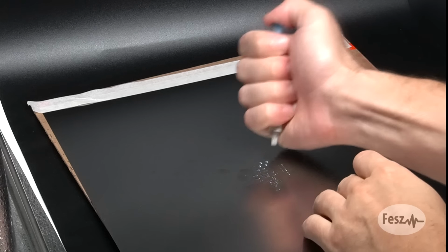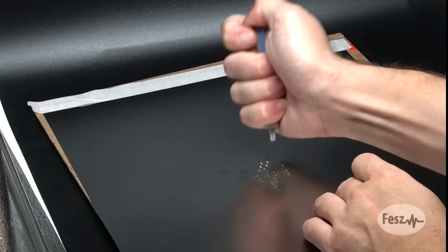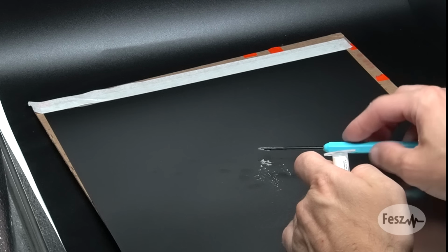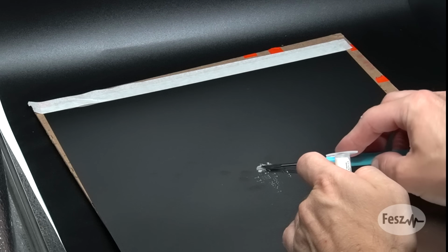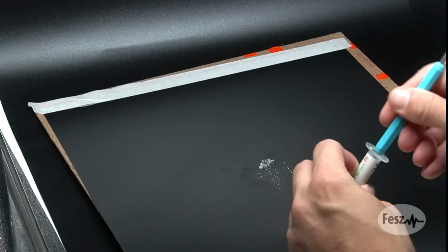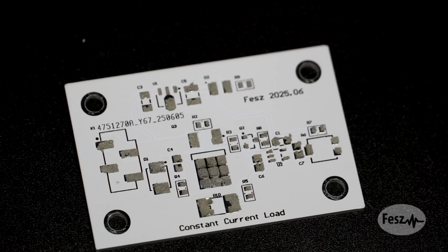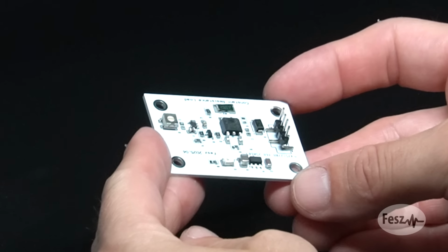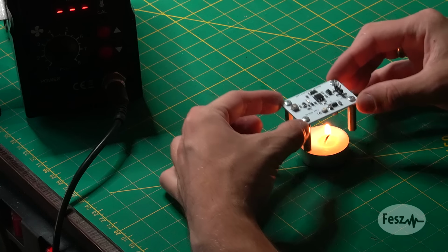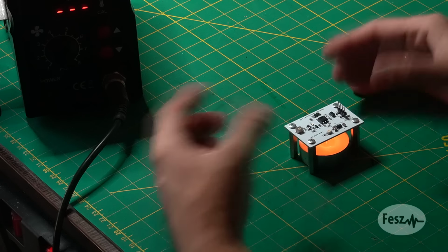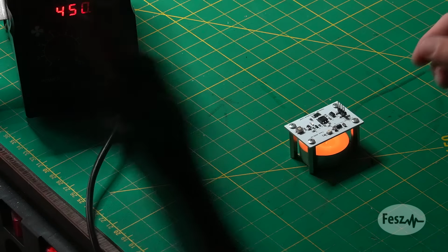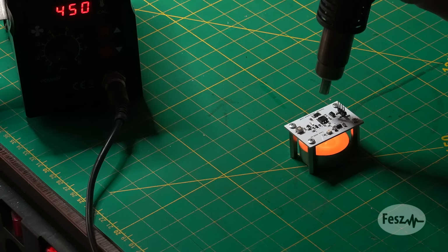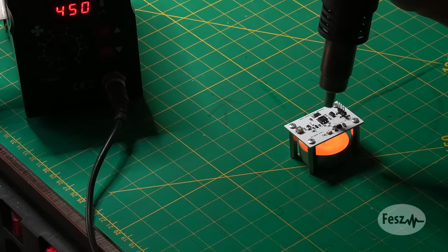Anyway, afterwards, I tried to apply some solder paste. And try I did. The issue was that the paste I had was opened years ago, and it wasn't really stored in appropriate conditions, so it got quite dry. Anyway, once the paste was applied and components were placed on top, it was time to somehow melt the paste. For this, I used a rather unconventional technique which I cannot really recommend. It's not that great. And you still need to combine it with some hot air. Regardless, the boards were assembled one way or another.